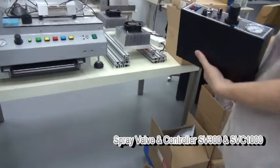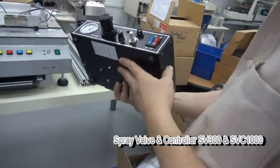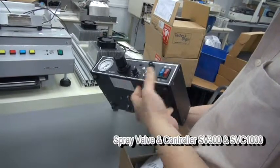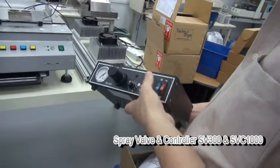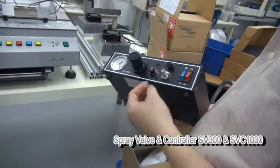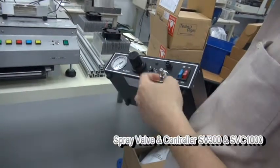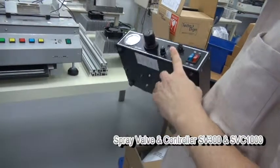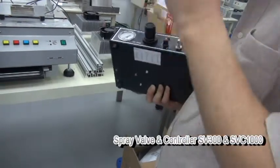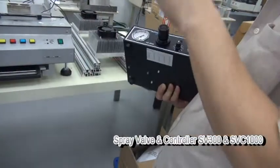This is the AD2000. This is the simplest one. So you just have a timer. This is on off. This is to set the timing. Pressure. Plug in. This is a vacuum suck back. I didn't explain this vacuum suck back. This vacuum suck back is basically to prevent leaking. It's a feature that helps you pull back the material.